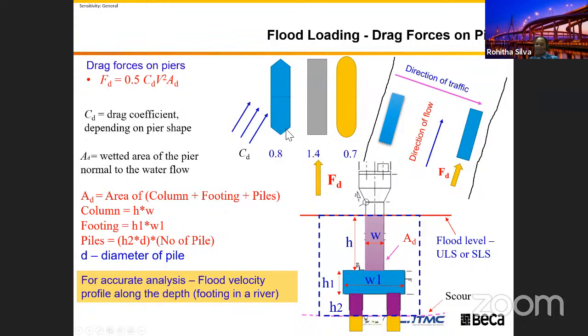again depends on the shape, right? So for streamlined shapes, like in the aerofoil, we use those shapes. That will reduce the drag force on your substructure. That's why when you are building bridges on creeks and rivers, you have a not rectangular shape. It's difficult to build, but you have the streamlined shapes in the construction. The rectangular shape gets the highest drag coefficient.